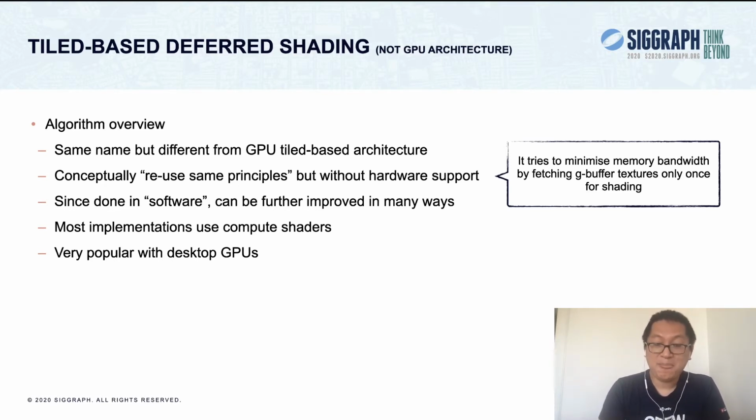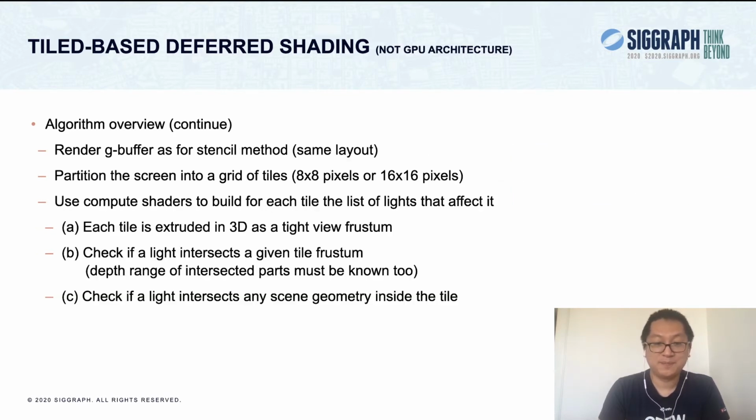But conceptually, it's the same as what you can do on a tile-based architecture, in a sense that it's trying to minimize memory bandwidth when you need to fetch the GPU textures for shading. But since it's done in software, it can be improved in many ways. So most implementations now use compute shaders, and it's very popular with desktop GPUs.